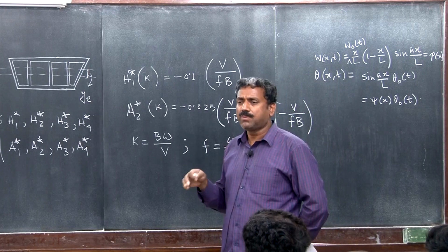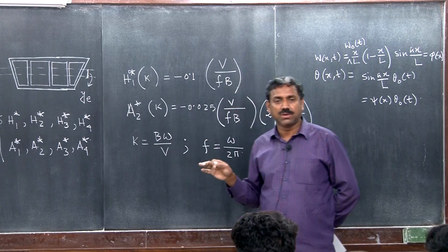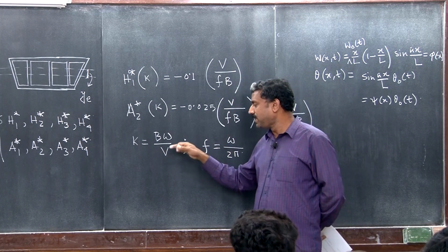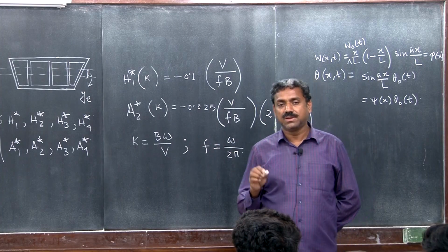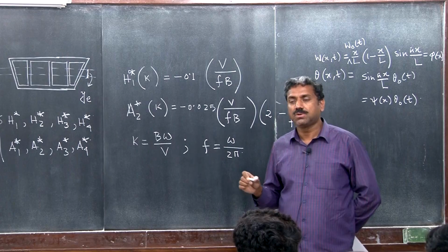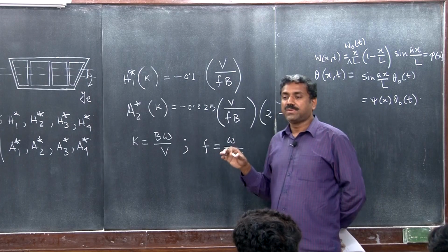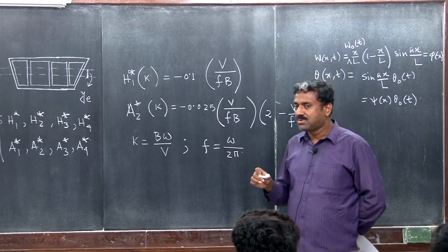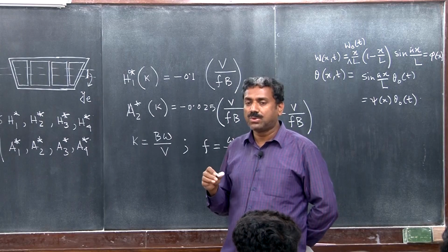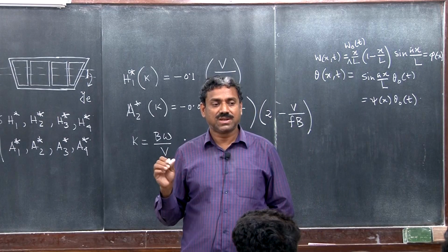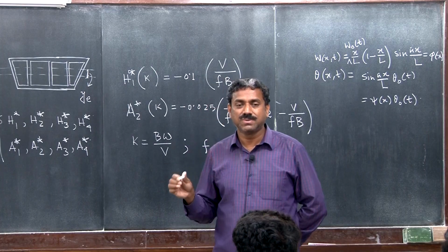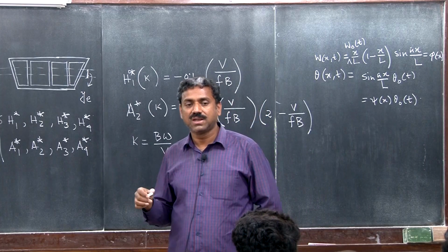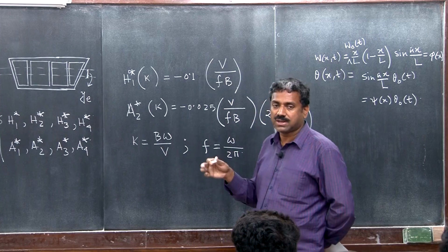Of course, that will have some influence, but if we consider the mean speed, the critical value of this mean wind speed that triggers instability is sufficient for design, because we want to design so that the critical velocity that triggers flutter must be above whatever wind speed can be realized there.